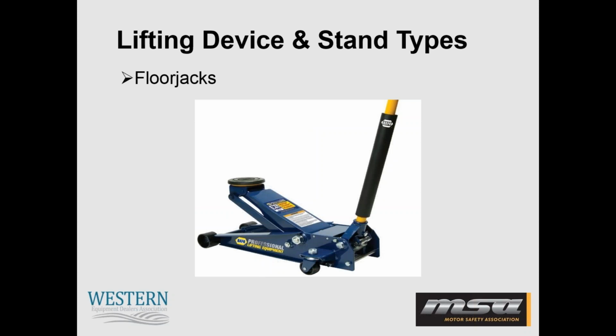Floor jacks. We see these at a lot of facilities that we go to. And when you are procuring or purchasing a floor jack, be sure to choose one that has a very large lifting pad. This will give your jack point plenty of surface area on which to contact. Also to be aware, because a floor jack is on wheels, it's going to want to roll into a sturdy position as the equipment rises. And that's perfectly normal. And once you've elevated your equipment with this floor jack, be sure to lower it onto jack stands before starting any work or going underneath that piece of equipment.